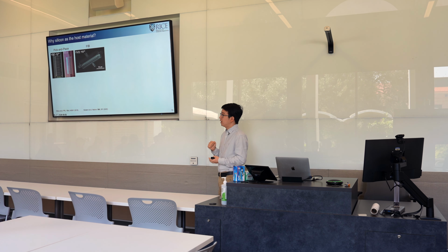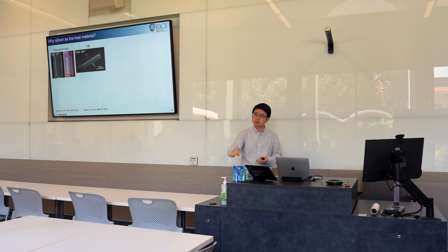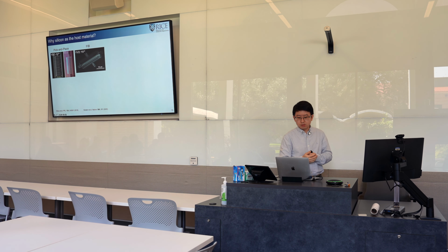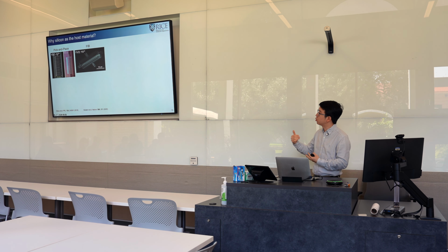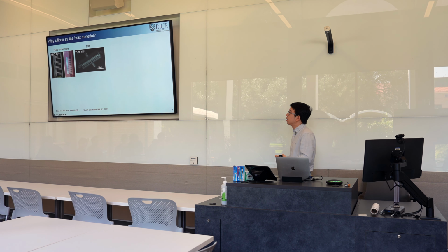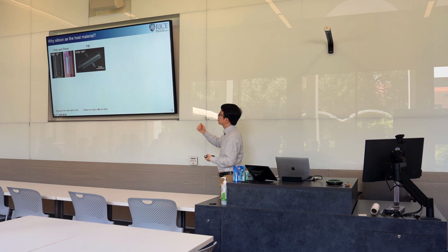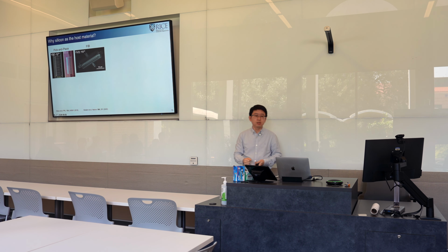You fabricate that device, and then you transfer it onto the oxide surface so that this device can interact with the erbium ions inside the oxide, okay? Or you can do this so-called FIB, which is short for focused ion beam. You can mill a device structure like what you are seeing in this picture.